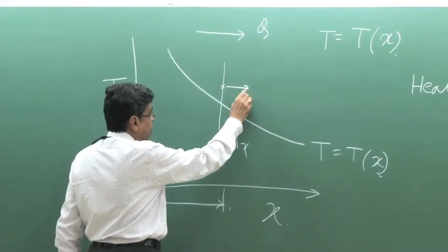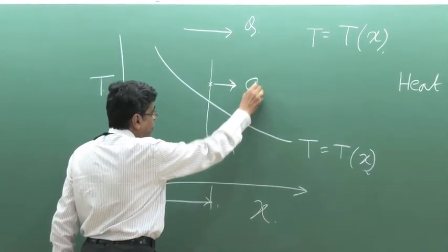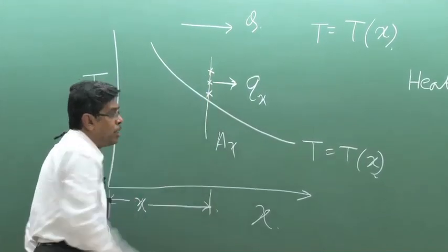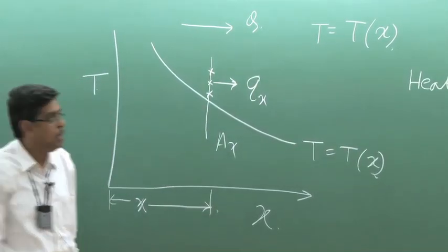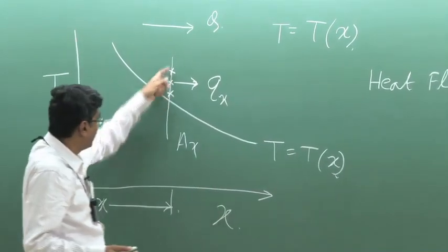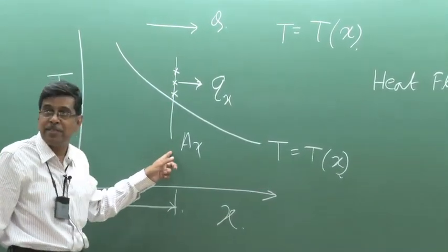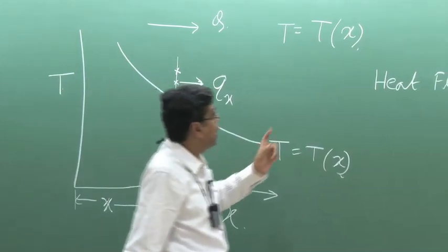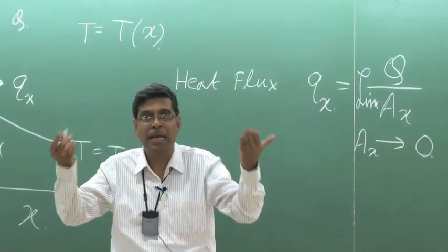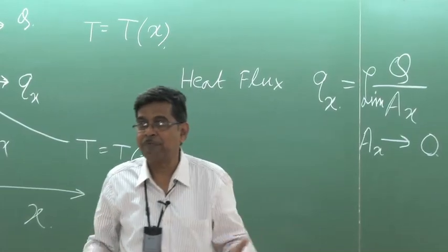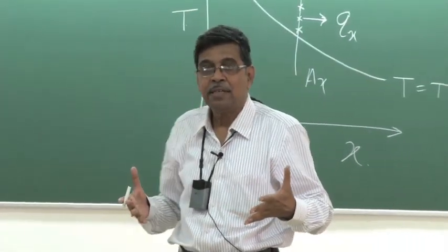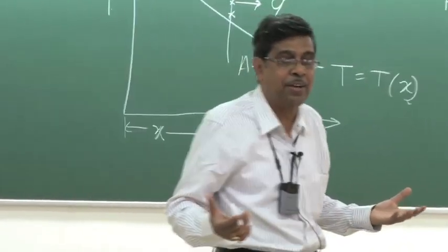That means here we have heat flux at a point. So therefore at different points we have different heat flux. It may be constant, may not be constant at all points on this area. If it is constant, then simply we multiply the area with the heat flux and get the total heat flow across the surface. But what is the difference with stress? Stress is a second order tensor.